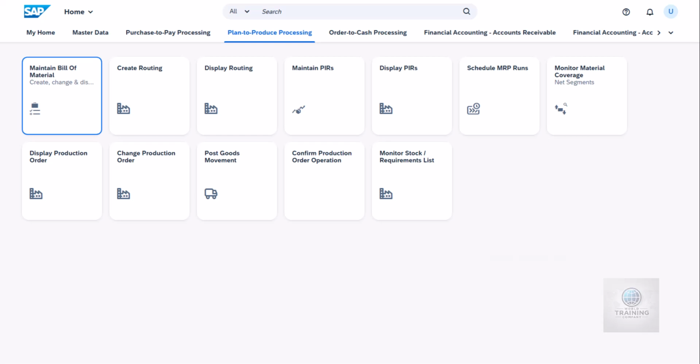We've just completed planning the independent requirements. Typically, these requirements are derived from operational sales planning or forecasts, which estimate future demand based on market trends and business goals. For this demonstration, we manually define the independent requirements. Now, based on these planned requirements, we'll proceed to execute the Material Requirements Planning, or MRP.